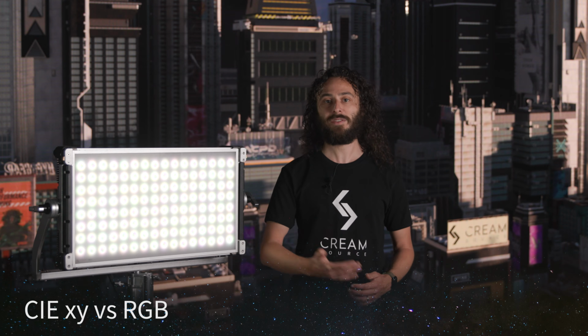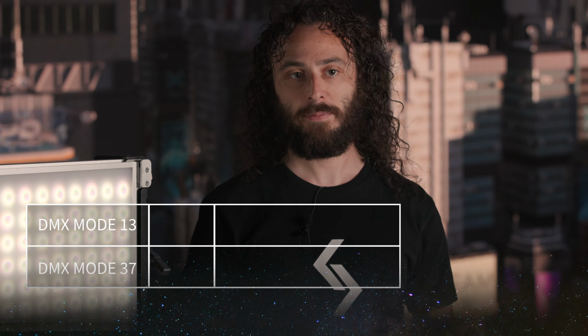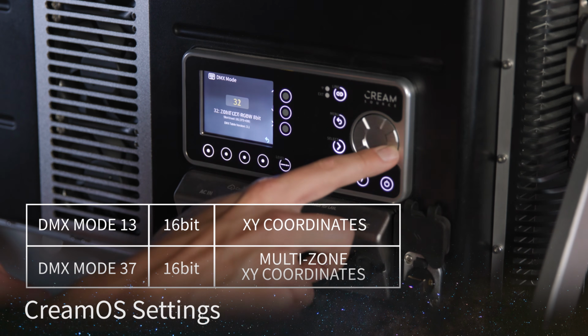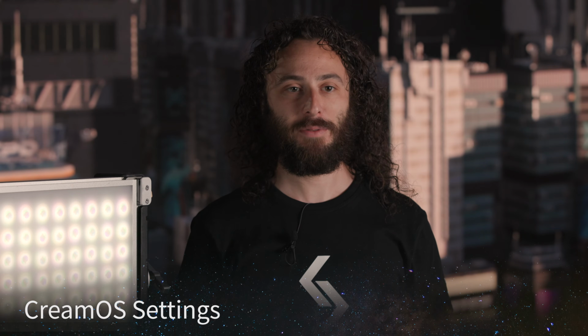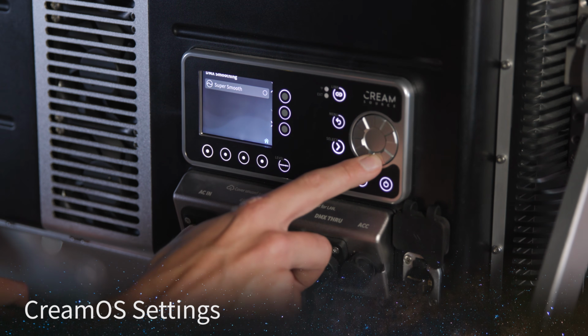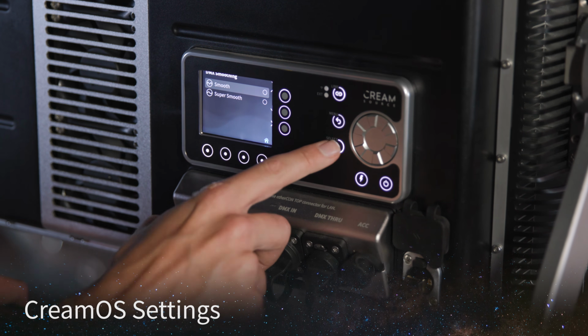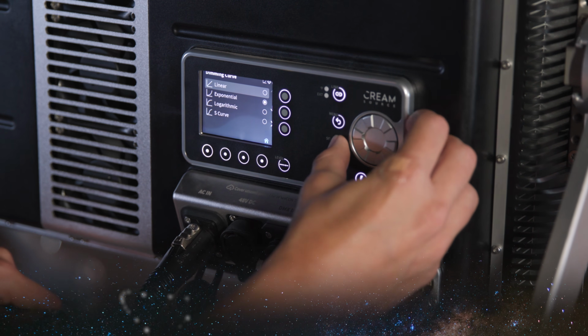And Live FX works with all color modes, but since the Vortex works natively with these XY modes, we'll be using a mode like mode 13 or 37. For this setup, we are going to put our vortexes in mode 37, a 16-bit multi-pixel CIE XY mode. The Vortex offers 3 levels of in-fixture smoothing: off, smooth, and super smooth. Today, I'm going to strike a balance by setting my DMX smoothing to smooth and my dimming curve to linear.